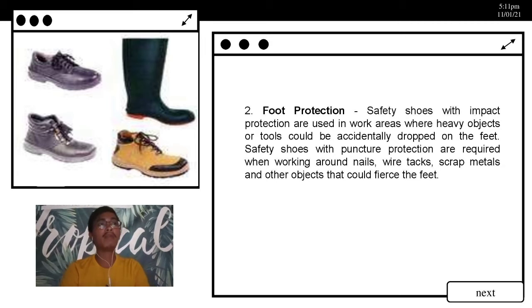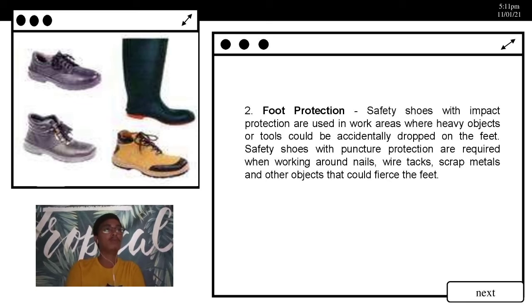The next one is the gray rectangle. This gray rectangle indicates a grade 2 protective toe cap with no puncture resistant sole. These are for industrial and non-industrial work environments not requiring puncture protection. So same with the blue one.